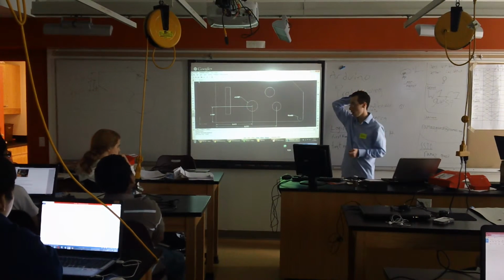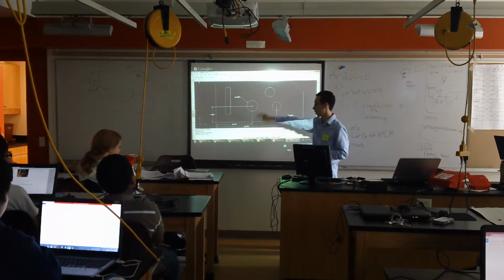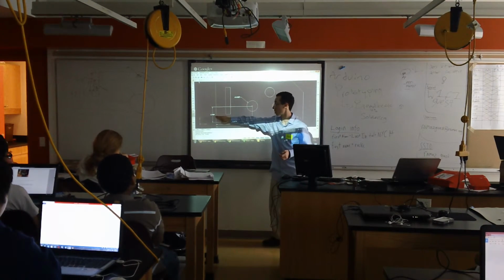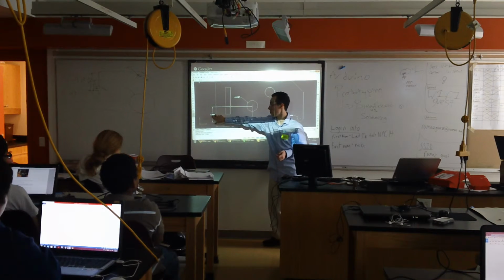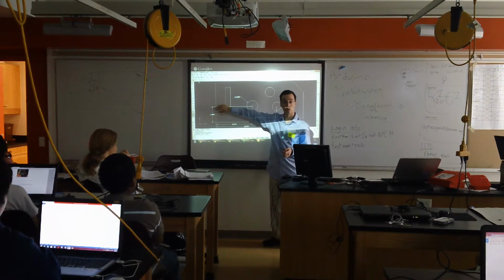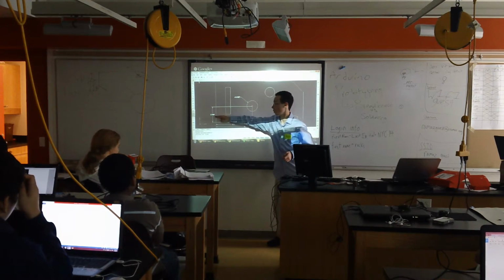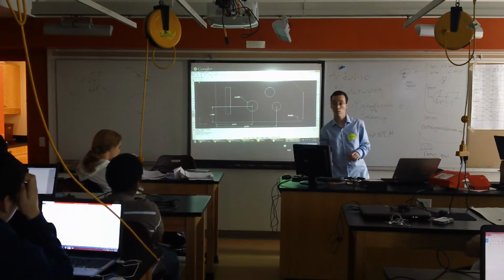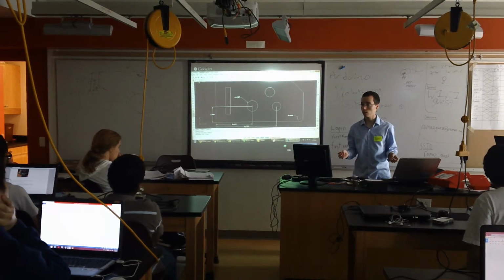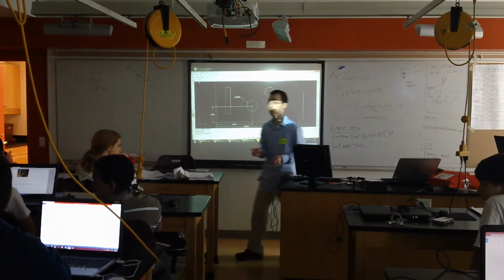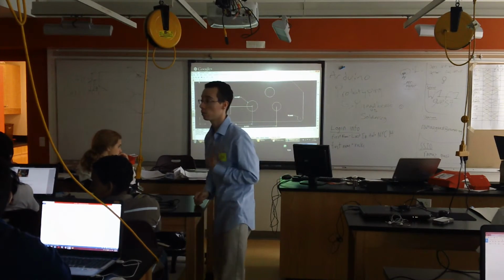If you're drawing them by hand, if you're doing it by computer, you won't have to worry about this. But if you're ever drawing by hand, you can be tempted to turn your numbers like this and have them line up with the way the dimension is going. But it's a lot more readable if all of your numbers are oriented the same way, like this. Any other questions about technical drawing in 2 dimensions? Oh, yes. A question about it in 3 dimensions.